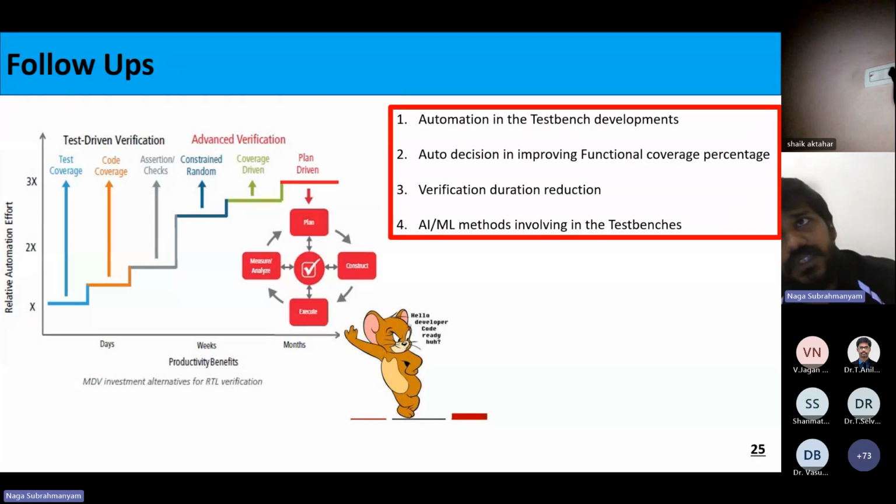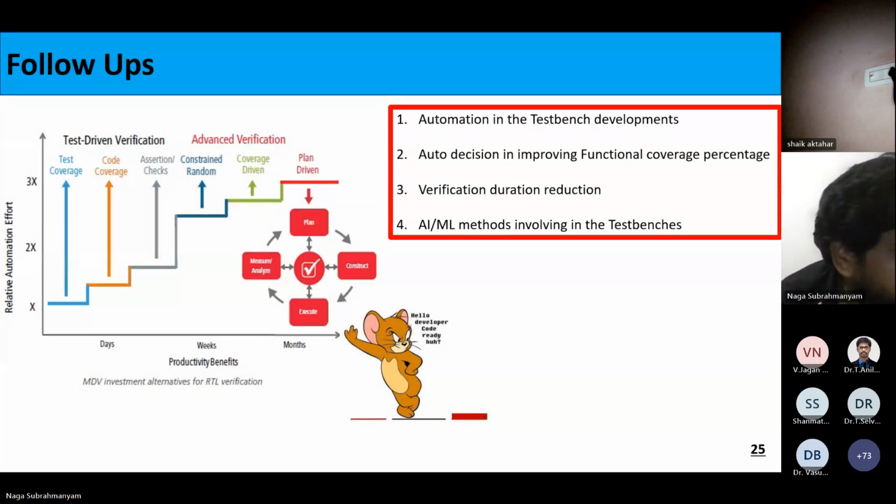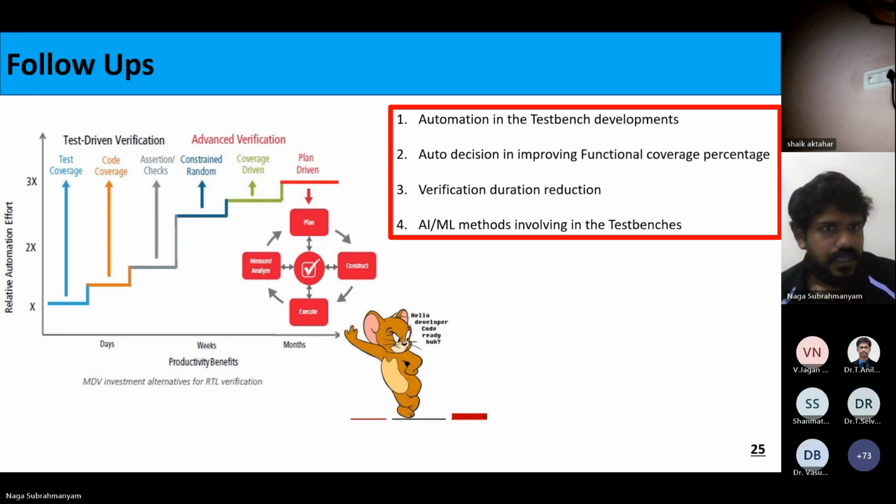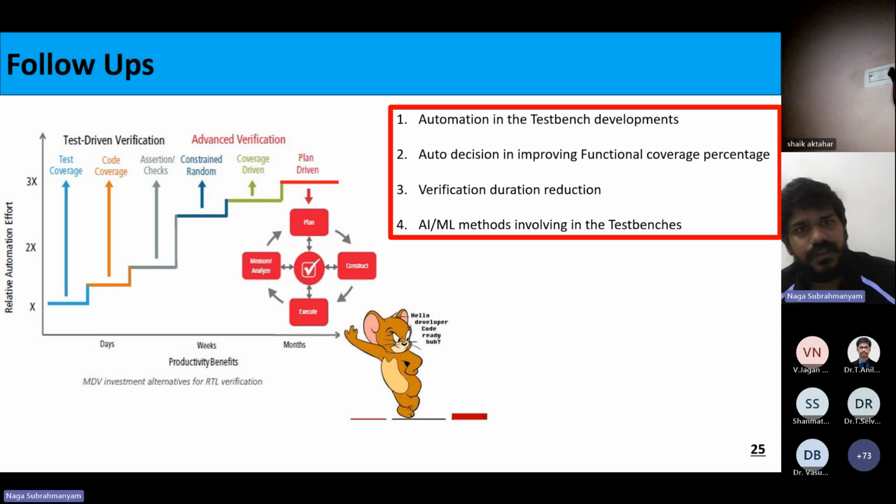In the states you have not verified, if any bug is there in the design, we are not going to find that bug. So that's it. Like that we will generate the data and understand what is covered: whether the entire design code is covered or not, and whether the entire design function is covered or not.